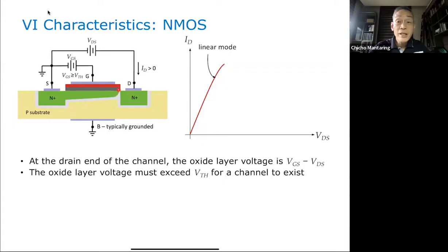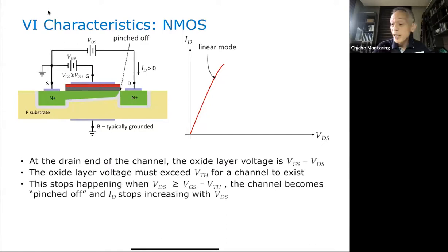And when the electric field here disappears, then we say that our channel has been pinched off. Ito yung pinch off niya. Kasi habang lumalaki yung VDS, lumiliit yung electric field dito, so yung channel dito nawawala. And that's what we call pinch off. And when that happens, increasing VDS further will no longer cause an increase in your drain current.